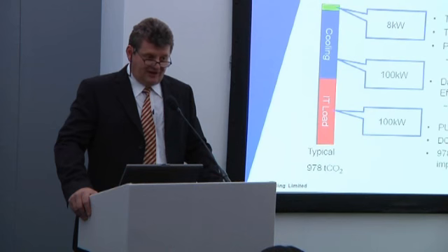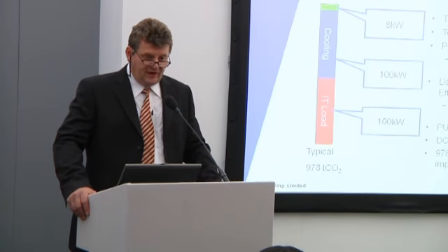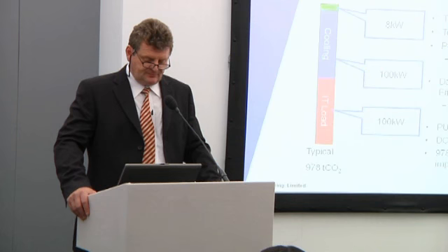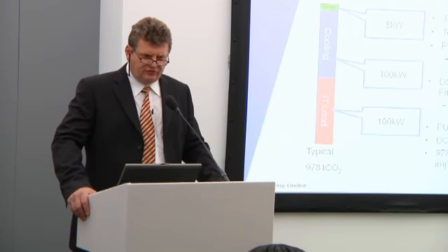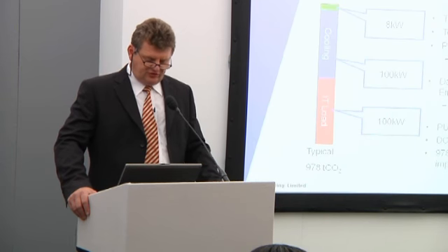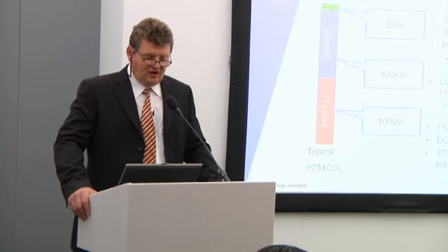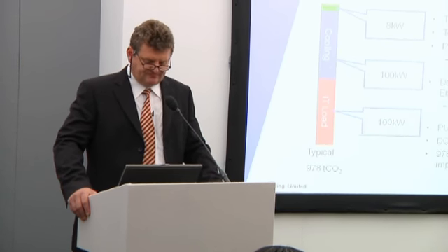Now, this is obviously an incredible cost, both in terms of the electricity usage and its carbon footprint, and also the consumption of the available power, where many sites have run out of available power. So, we look at this ratio called a PUE. You'll also come across another expression called a DCiE, data centre infrastructure efficiency, which is purely the inverse of it. It's like a percentage efficiency.